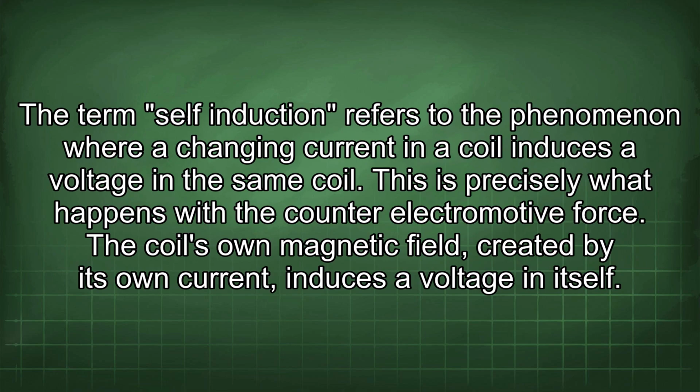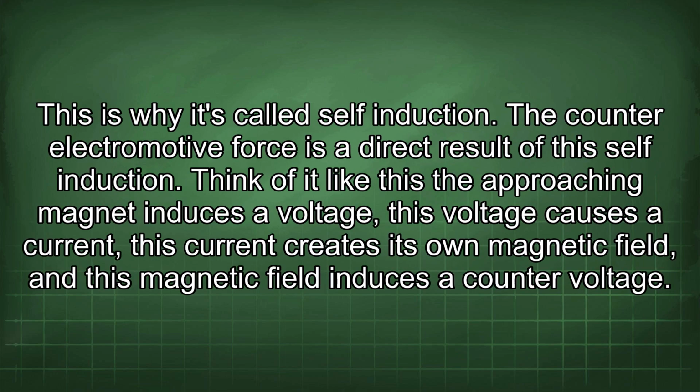The term self-induction refers to the phenomenon where a change in current in a coil induces a voltage in the same coil. This is precisely what happens with the counter-electromotive force. The coil's own magnetic field, created by its own current, induces a voltage in itself. This is why it's called self-induction. The counter-electromotive force is a direct result of the self-induction.